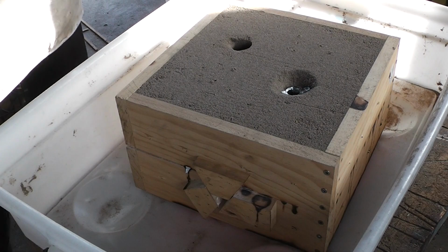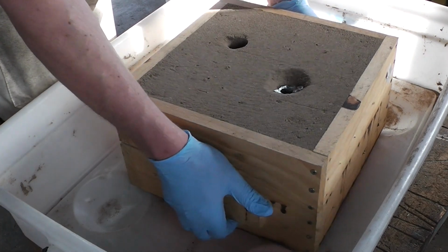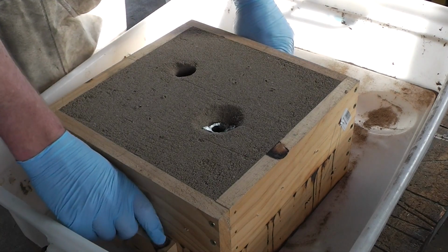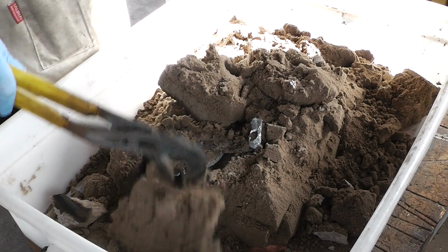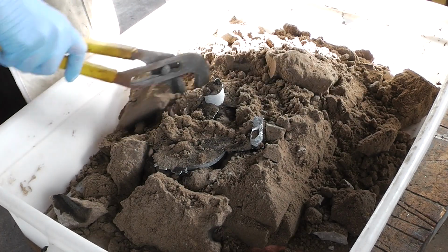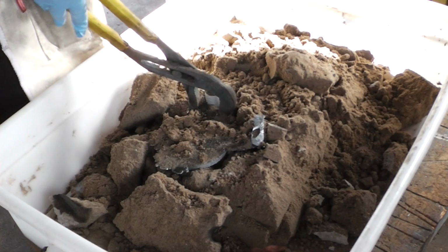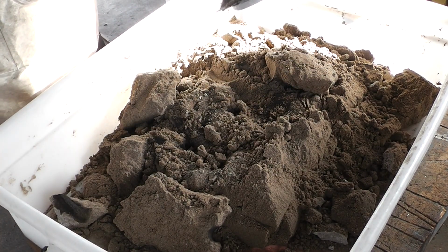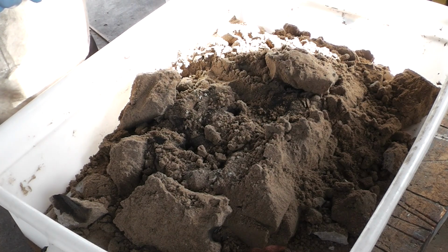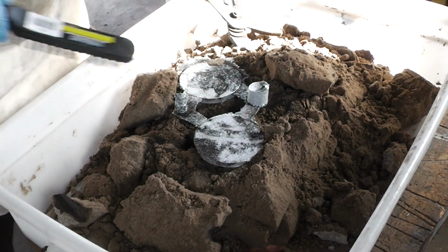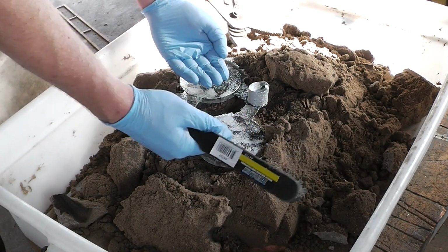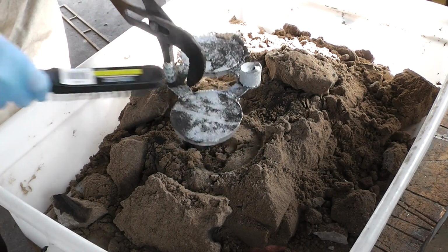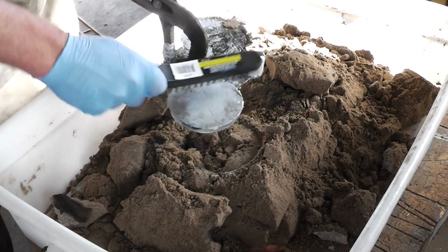Right, I forgot to put a weight on top of this one, and so there was a blowout out the side. I'm hoping that it worked out despite that. Yes, I think I got away with it. They're wide and flat castings, so there would have been a lot of pressure pushing the cope up, which is why they would have had a blowout like that.